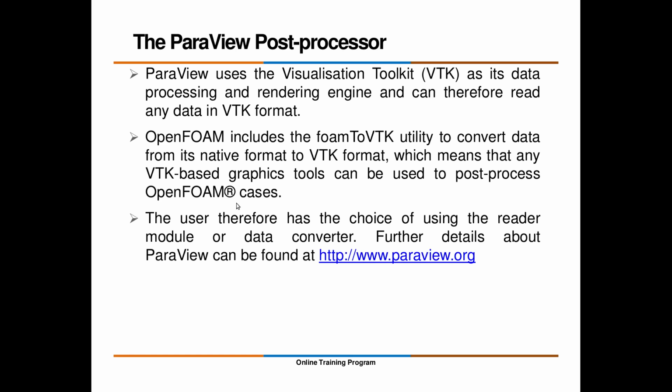Then when we talk about pre-processing as a mesh generation solver and the post-processing, without post-processing our simulation is not complete, okay. So no worry with OpenFOAM. OpenFOAM comes with its inbuilt or adapted ParaView as a post-processor. This ParaView is basically open source, and in OpenFOAM they created a wrapper over the ParaView and it's called ParaFOAM, okay. So we're going to work with ParaFOAM, but in the background ParaView is working, okay. It uses the VTK toolkit, and it works with the VTK format.